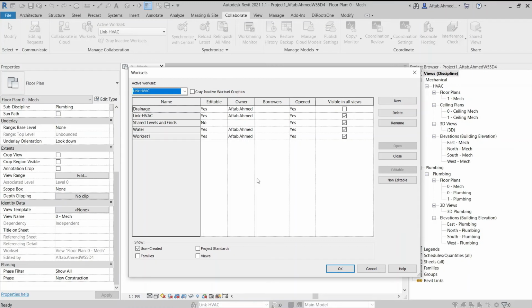The editing request dialog box will be received by the workset owner, which will contain the description of the element and the name of the user who wants to edit the element. The workset owner can view this element with the Show button, and he has the right to grant or deny this request.